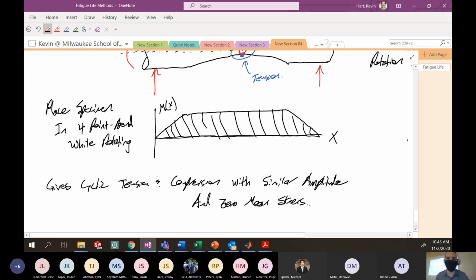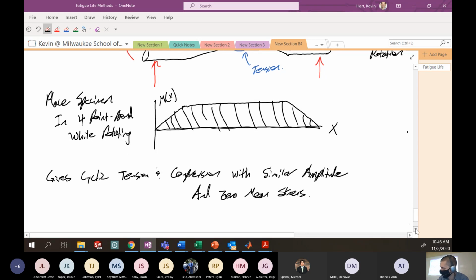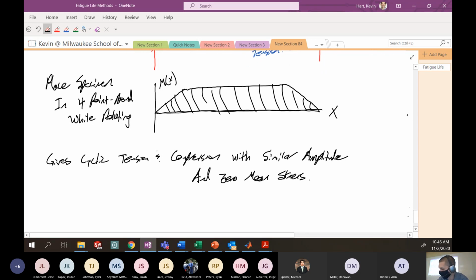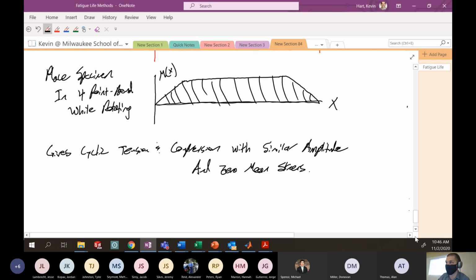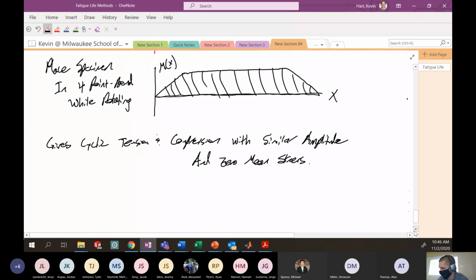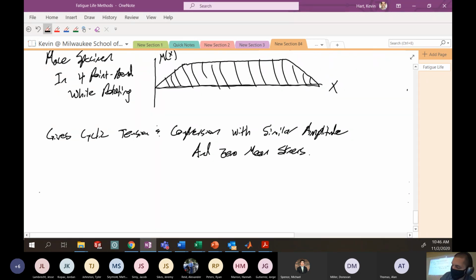Okay, so you just load this thing in 4-point bend. You get some motor at like a zillion RPM, and there's an encoder on the back end of the motor, counting how many spins that you're doing. And then as soon as this thing fails, your encoder stops counting and it tells you how many cycles you have to failure. Pretty slick test. If done well, it actually only takes a matter of like maybe a couple minutes for like a million cycles. It's pretty cool.